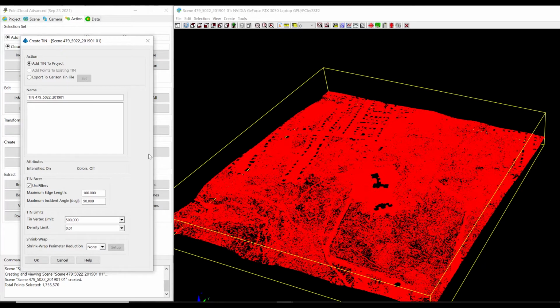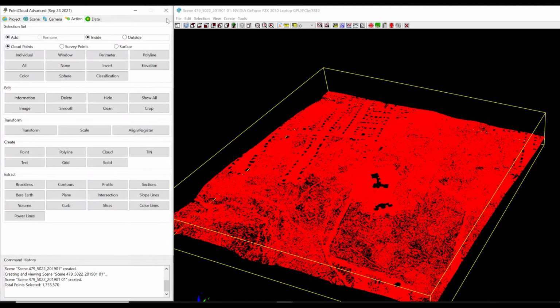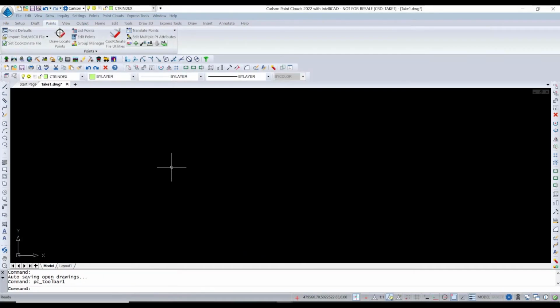Okay. And this is basically a way to very quickly use LiDAR data, if it's classified, to do some special things. Most importantly, in this case, is to create essentially a bare earth ground tin from a Lidar that has lots of other data.